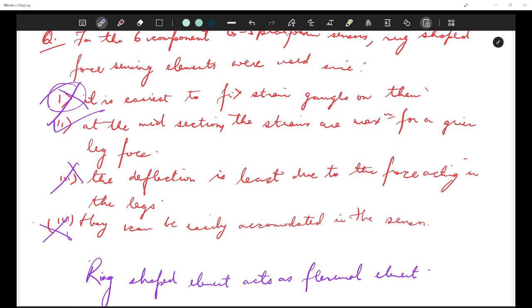The other option is it can be statically isotropic. Okay. Static isotropy means equal force sensitivity in all the 6 directions. Condition number of H would be equal to 1. So, special geometries can achieve static isotropy. So, a traditional 6-6 platform can be statically isotropic. Therefore, the statement is not selected as universally true or false in this context.